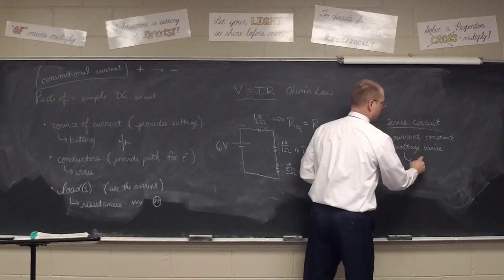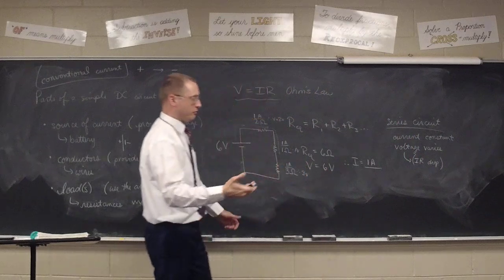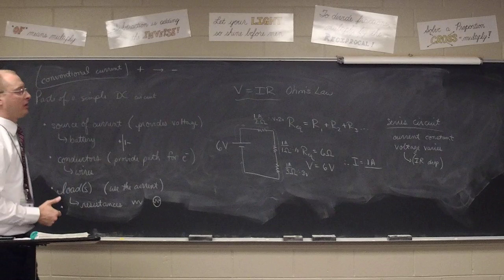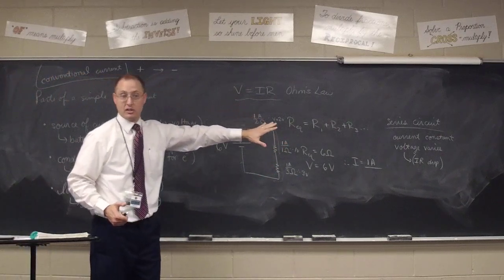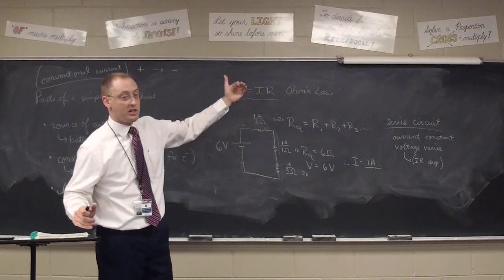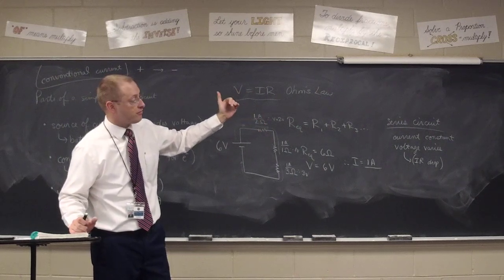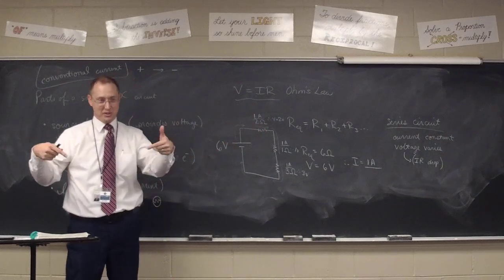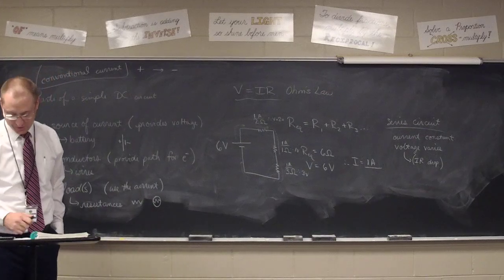varies. By the way, voltage is sometimes referred to as the IR drop. There's a drop in electrical potential difference. Or V is IR, so IR drop. There's an IR drop at each resistance. Now the nice thing about this is if you think English class, listen, for a series circuit, current is constant and voltage varies. Makes it easy to remember. You see what we did there with the alliteration? Okay. That's going to help you remember that, I hope, as we go forward.